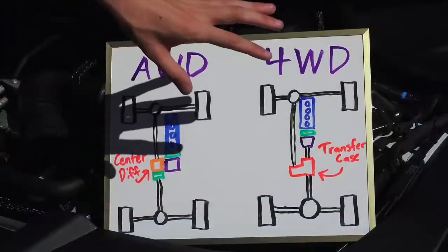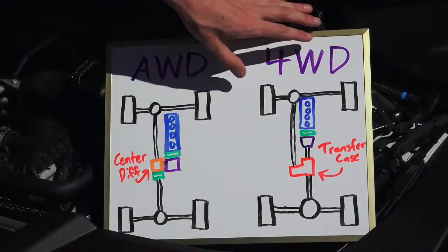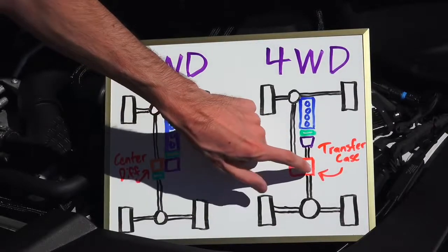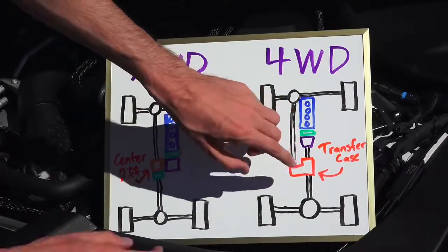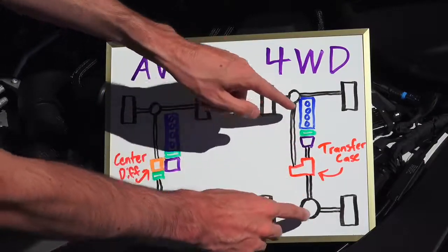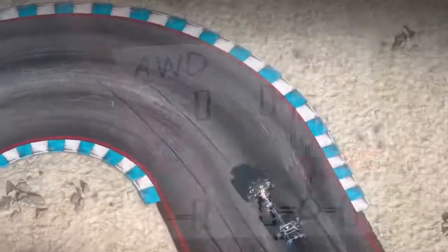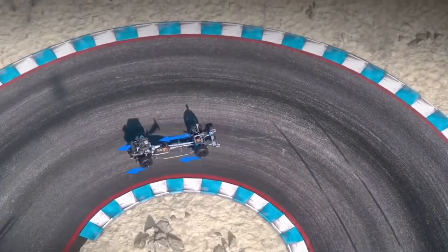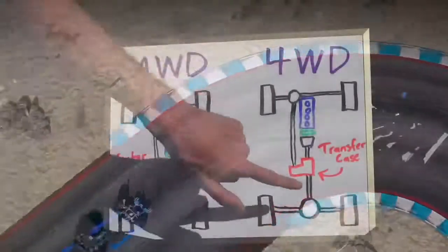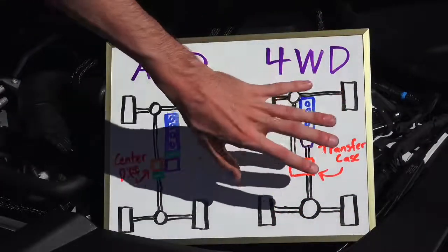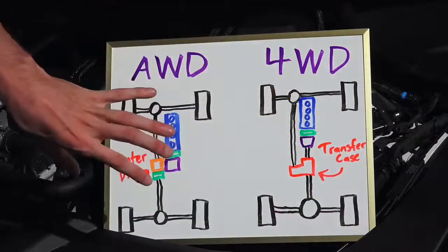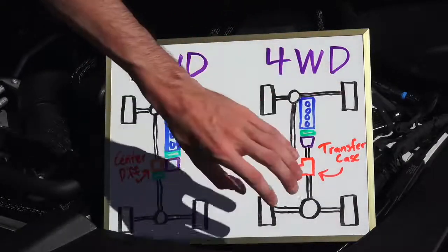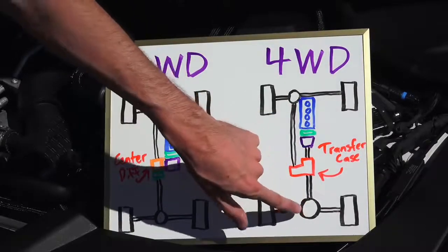So does all of this mean that the BMW M5 can't use four-wheel drive on the road? Well, no, actually they've done something super clever. They've put a multi-plate clutch within this transfer case, and what this does is allow for a different torque split and varying speeds between the front and the rear axles. So it can send different speeds to each axle, and as a result, you can go around corners without binding this transfer case, and you can fully vary the torque distribution. That's a really neat thing that BMW's done. It acts a lot more like an all-wheel drive system when it's in this four-wheel drive mode, but it has that traditional transfer case where you can select to just use those rear wheels.